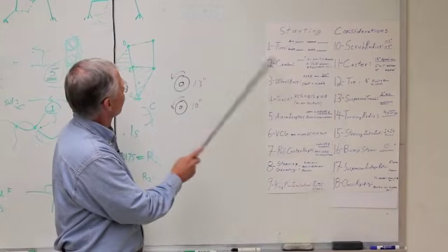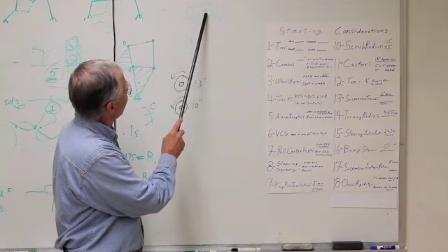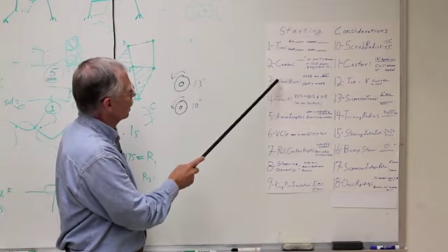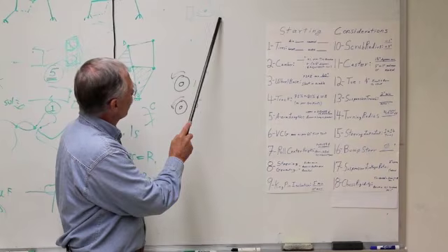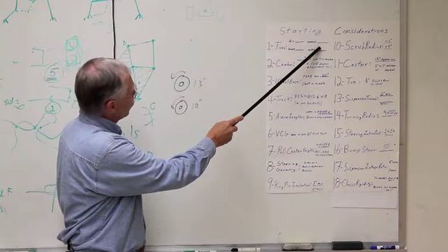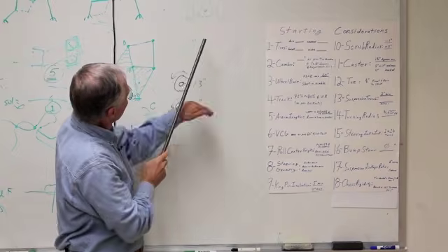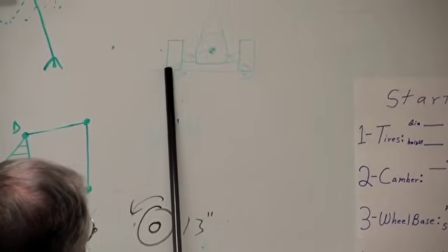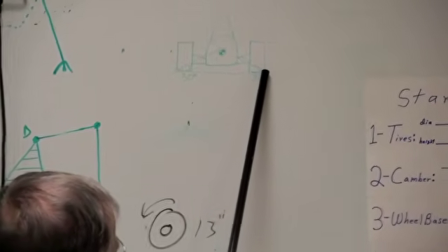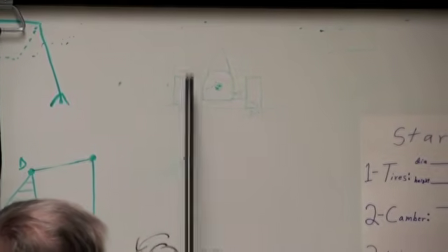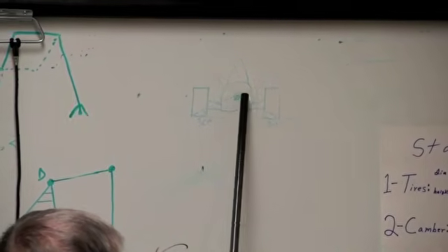Now, if the car is going to be tilted 60 degrees, we can find the maximum height our center of gravity can be as long as we know the track of the vehicle and the width of the tires, which we've already decided upon. And guess what? If it's going to be tilted up 60 degrees, that means we go to the outside of the tires on each side, ground level line, come up at a 30-degree angle, where they cross.